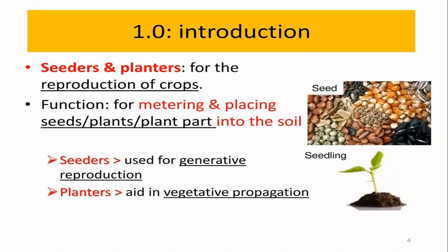It will move the seed from the hopper to the seed metering device. A very important step or metering tool is called the seed metering device. The seed metering device takes seed from the seed tube and places it in the proper place, put the seed in a proper place. It's called metering and placing, right? Into the soil. You know soil is very important, right? Soil is very important.